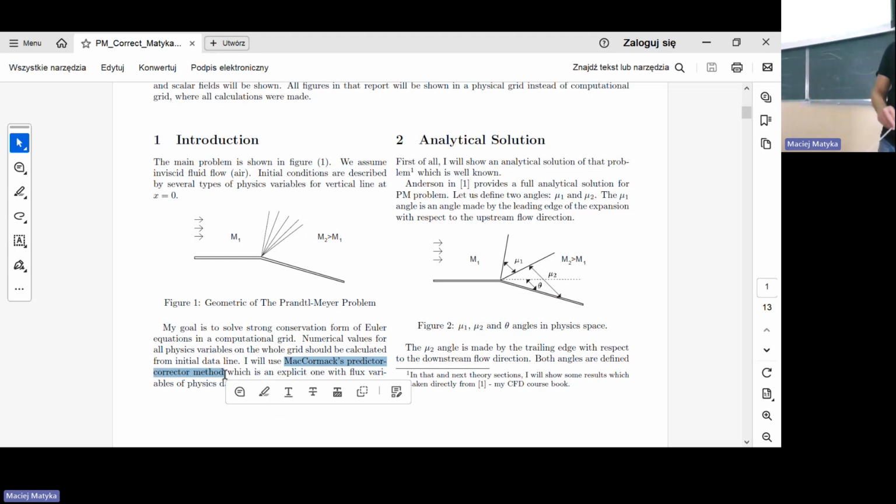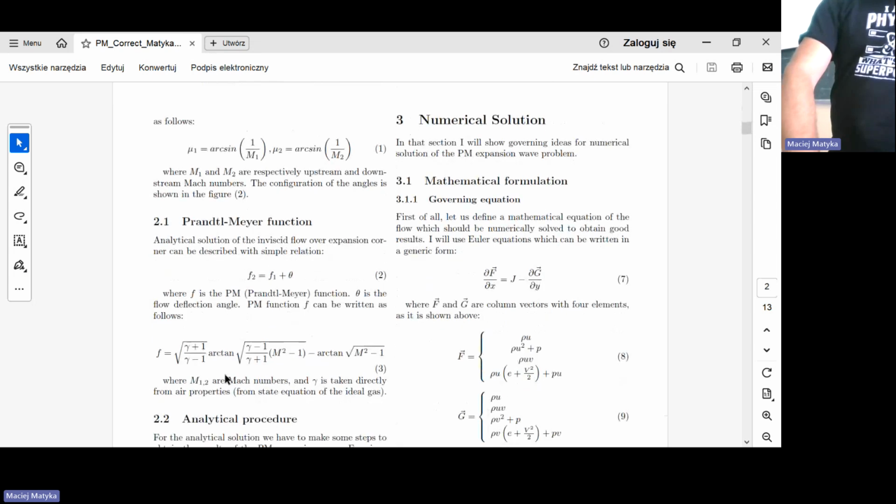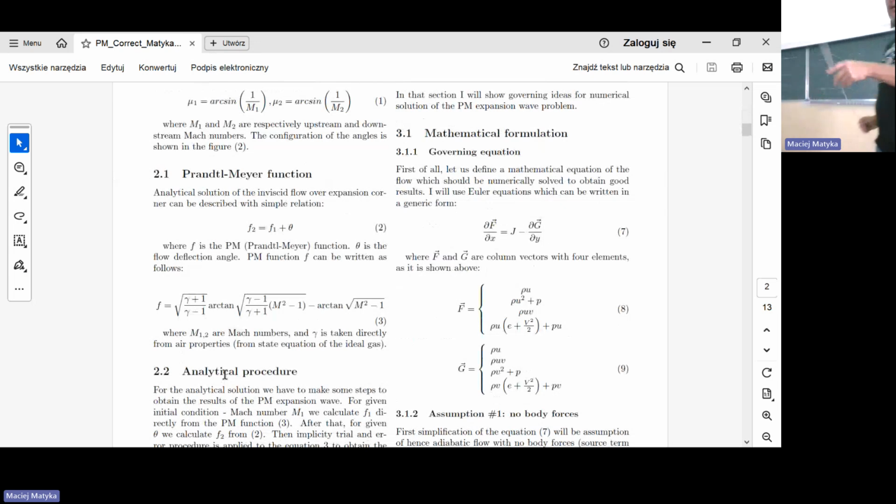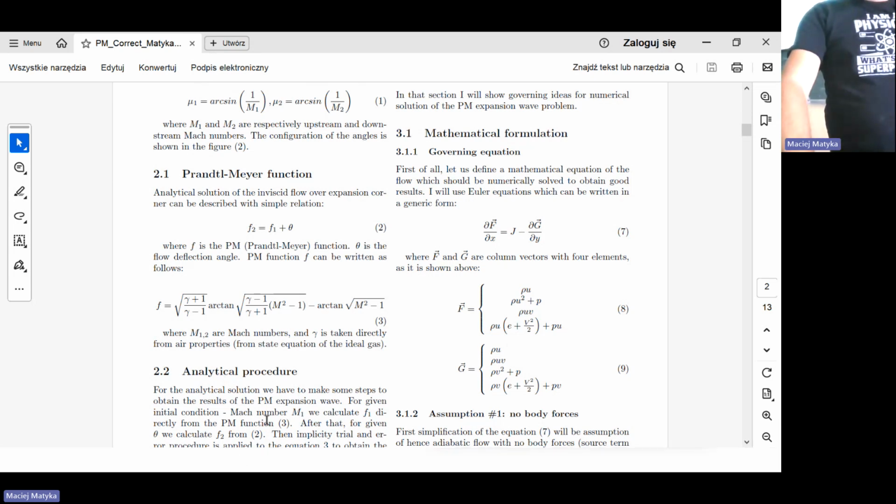Numerically, this is the MacCormack method. So it's again marching through the system, step by step. The equations I solve are here. These are the Euler equations written in this simplified form. They are written like this because then we basically go through the solution for f and g in parallel. It's like a bundle of physical parameters that we solve for. It's a pretty complicated equation. Basically, all this goes here, and of course, all this goes there. And then if you do it, you have the Euler equations. I don't go into the physics there. There are also some assumptions.